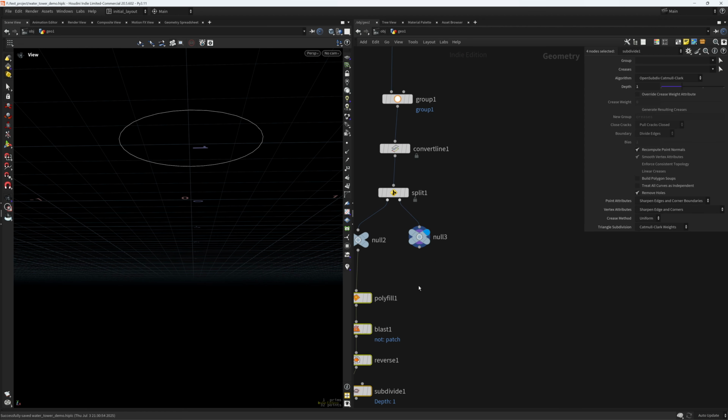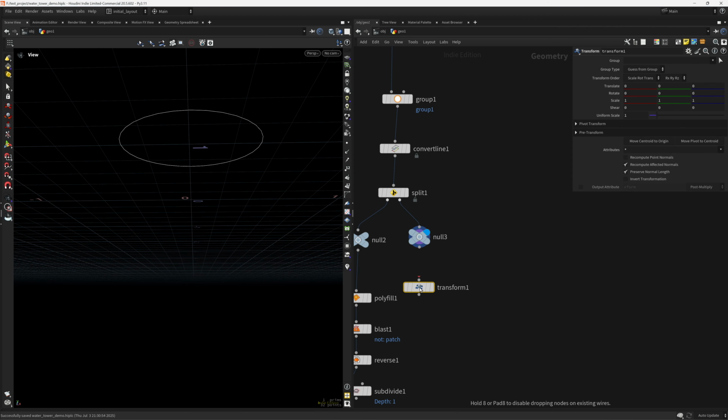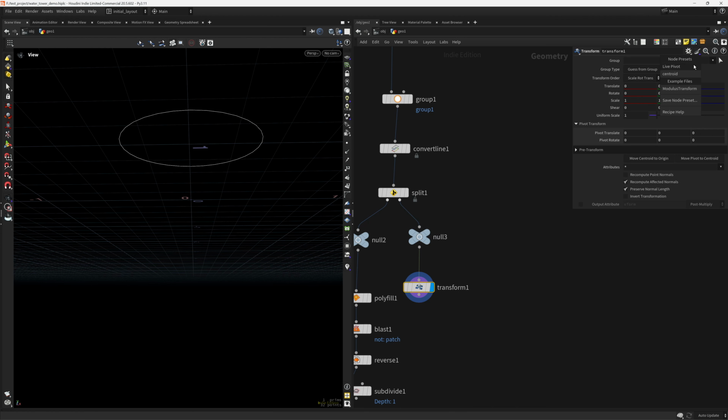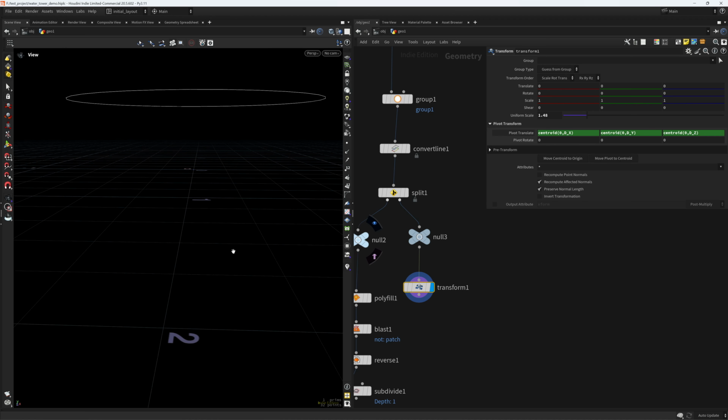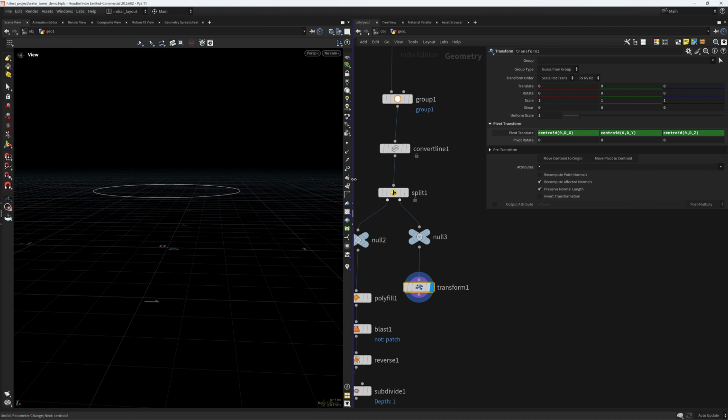Now for this one, I want to scale it a bit up to create the cone at the top. So for that I'm gonna create a transform. And in the pivot I need to enter centroid. I have a preset in here in my recipes, centroid. You just need to write these expressions in here, so it scales from the center. Otherwise it will scale from the world center, and it will move the geometry. So I'm gonna scale it by 1.15.